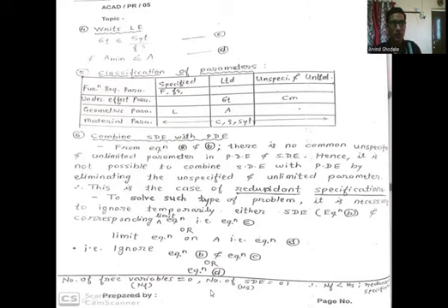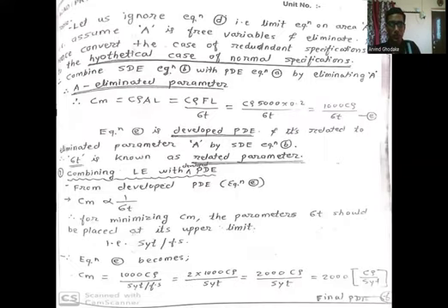So to solve such a type of problem, it is necessary to temporarily ignore either the subsidiary design equation and corresponding limit equation, that is equation C, or the limit equation on A, that is equation D. That is, ignore equation B and equation C, or ignore equation number D. Therefore, the number of free variables NF is equal to 0 and the number of subsidiary design equations NS is equal to 1. So here NF is less than NS, so it is the case of redundant specification.